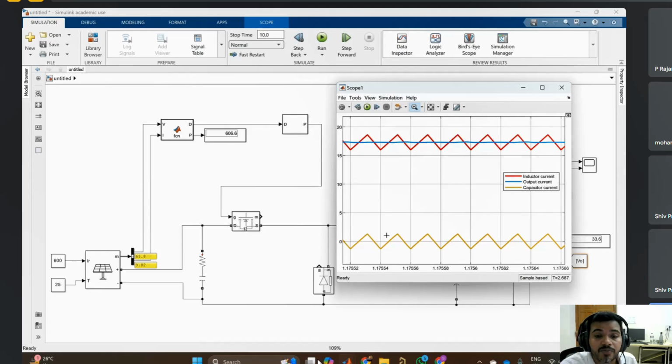Same thing, the average of inductor voltage in a switching period will be 0. These two are known as flux balance and charge balance. If both are not satisfied in your circuit, then you can't operate the circuit. It is a DC-DC converter, and input voltage and output voltage are both DC.